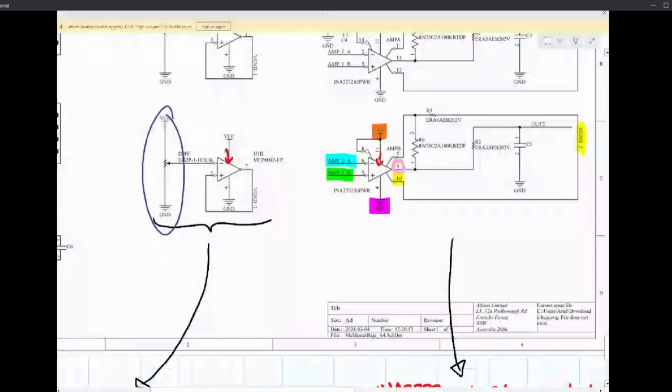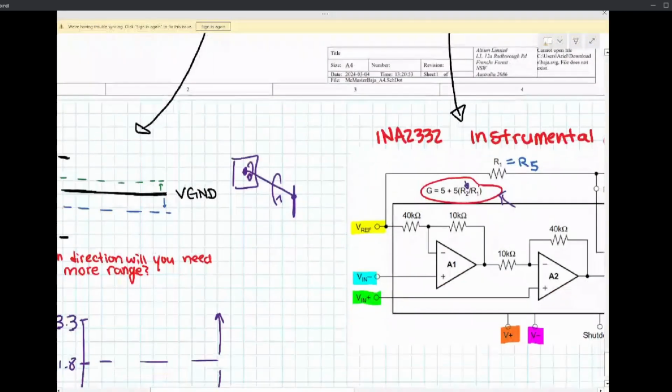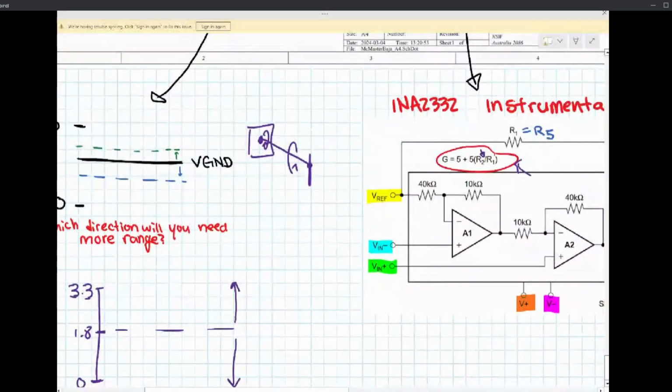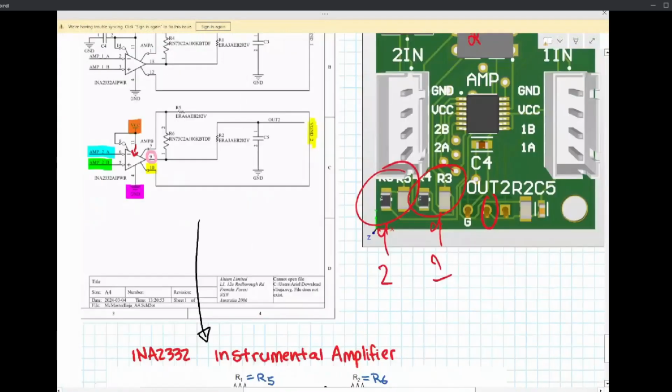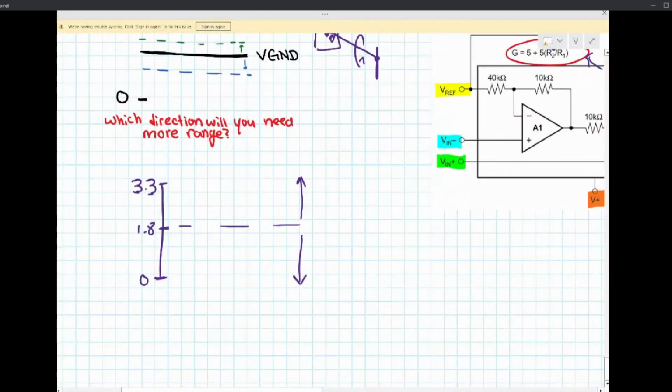Actually, yeah, I think it is. By adjusting your offset, like the value of the two resistors on the string PCBs right now, or by turning the trimmer pot on some of the newer PCBs, you're going to adjust where your virtual ground sits. So if your virtual ground sits at, let's say, 3 volts, you're going to saturate at 3.3 super fast in one direction, but you're going to have so much more granularity in the other direction. You're going to be able to see the loads, or the torques, in a much more granular way, and you're going to have access to more of that range.